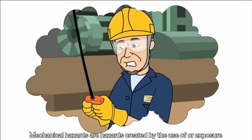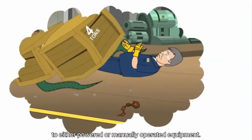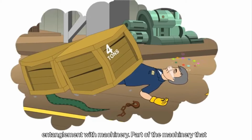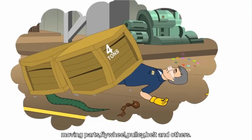Mechanical hazards are hazards created by the use of or exposure to either power or manually operated equipment. Mechanical injuries are mostly caused either by contact or entanglement with machinery. Parts of the machinery that could be hazardous to workers include sharp edges, hot surface, moving parts, flywheel, pulley, belt, and others.